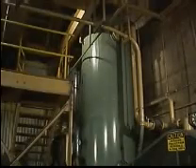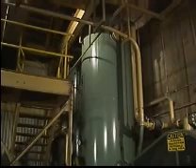Compressed gas that is clean and dry is usually stored until it is needed in the facility. Typically, containers called receivers are used for this purpose. Receivers are large tanks that store compressed gas so that compressors don't have to operate continuously. In most facilities, the demand for compressed air and other gases varies greatly, and the pressure in the compressed gas system can vary with demand. To keep the pressure from rising uncontrollably, some method of regulating the pressure must be used to control the amount of gas that is delivered by the compressor.